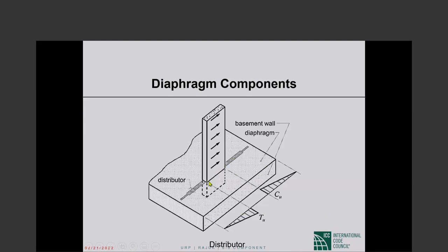Okay, so the base shear will cause shear stresses in the diaphragm. You can imagine the shear stresses, and the shear stresses build up to tension in this part, and it is large compression here and then decreases to zero. This is the opposite of the collector, many times called the distributor, but the same principle. These reinforcing bars are absolutely needed to take the base shear into the diaphragm, and then from the diaphragm it goes to the basement walls where they are resisted.